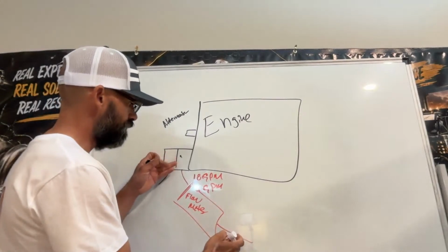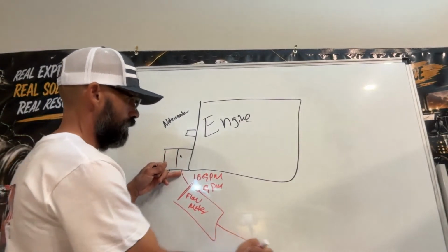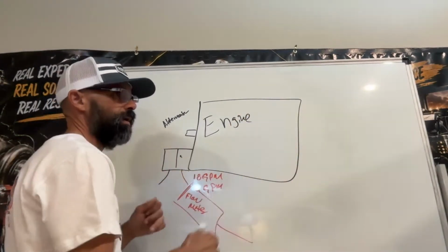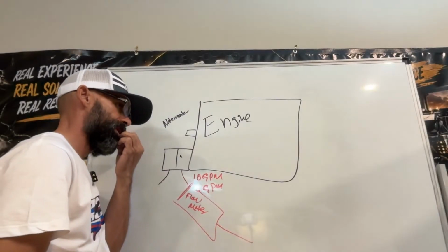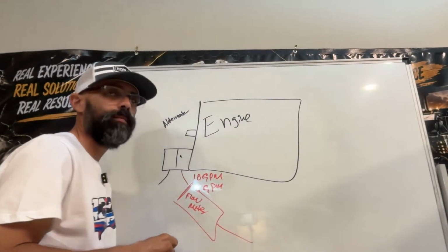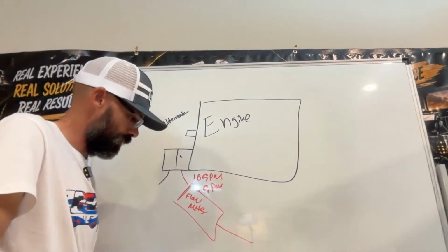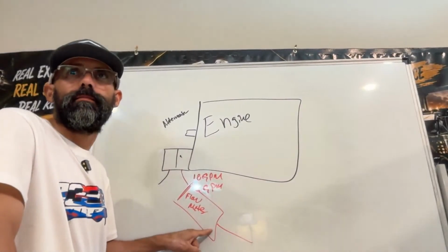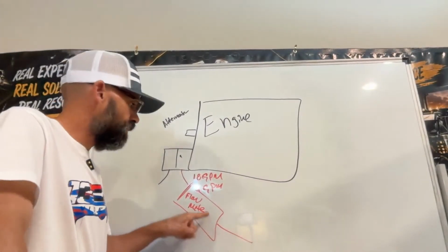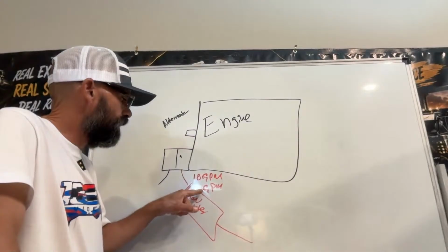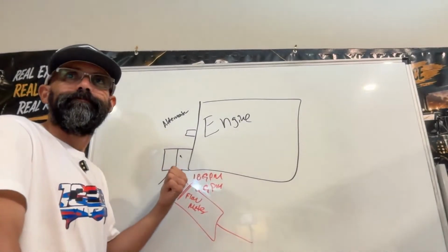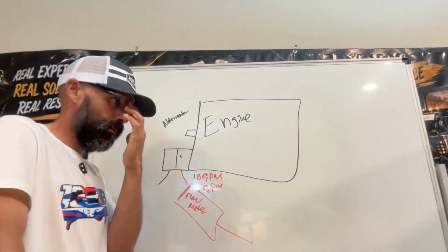You're gonna tee it off from the pump, right, on the line to the tandem pump or the pump itself. This is not gonna lie, because if it calls out for 18 GPMs and you're getting only 6, then you have an issue on that pump.